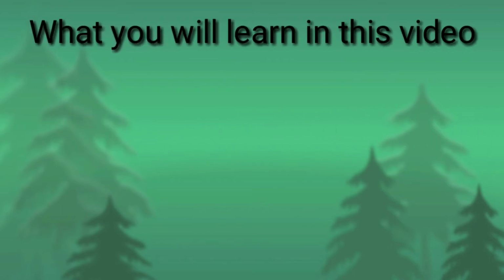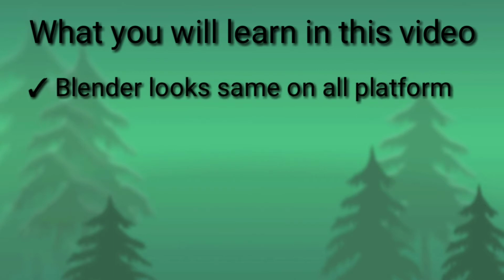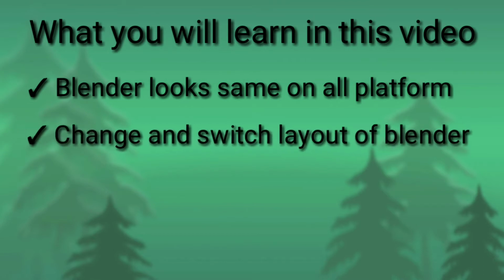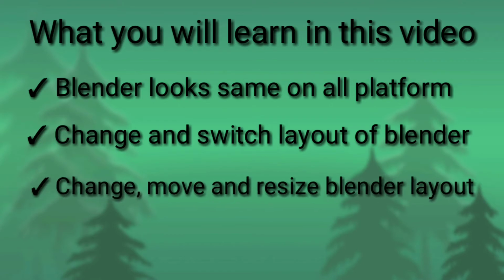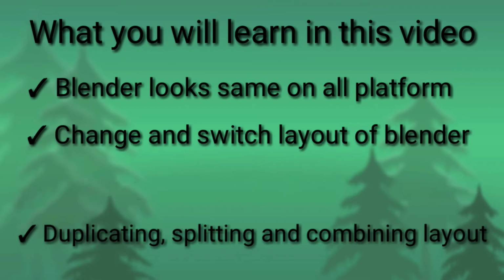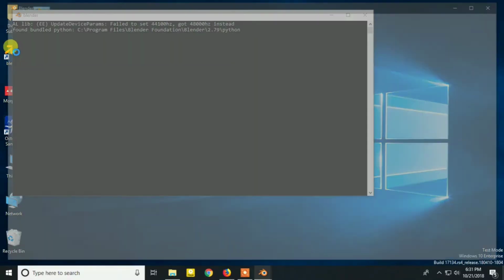In this video you will learn the following. Blender looks the same on all platforms, either Windows or Macs or even Linux. You will learn to switch and change the layout of Blender. You will change, move and resize the Blender layout. You can duplicate the layout or split one layout into multiples, and finally you will learn to combine these layouts into one.